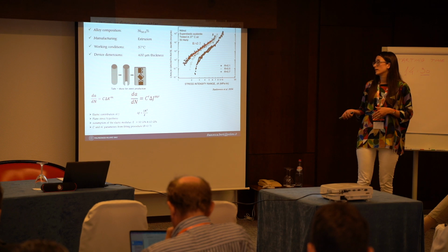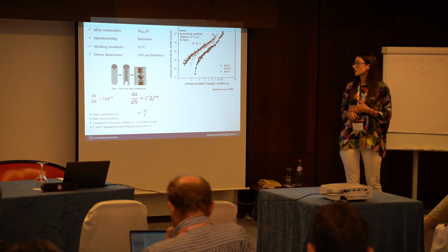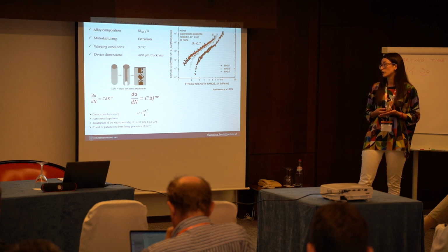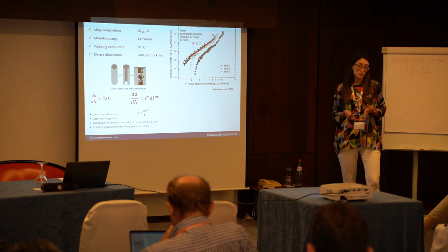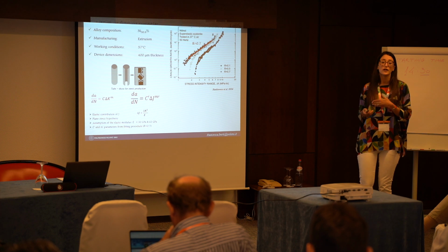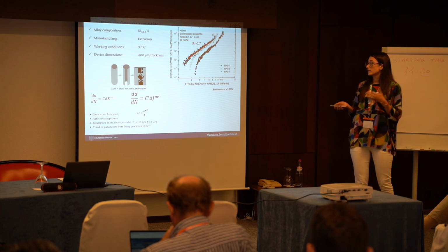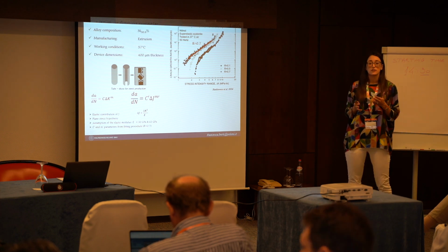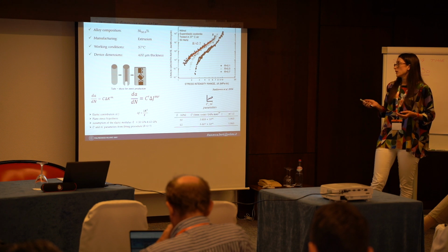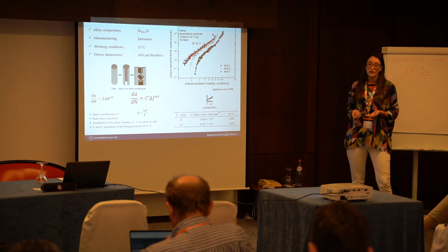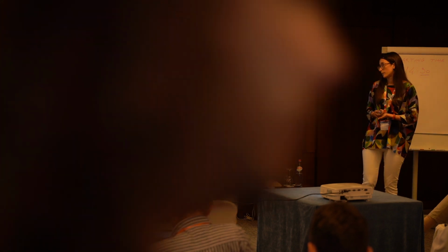and we converted the information in stress intensity range into the cyclic J integral, making some hypotheses, just considering plane stress and the elastic contribution of the J integral. Since we needed the value of the elastic modulus of the material, and in this work it wasn't available, we selected 2 cases, 50 gigapascal and 62, that are reasonable values for this material.